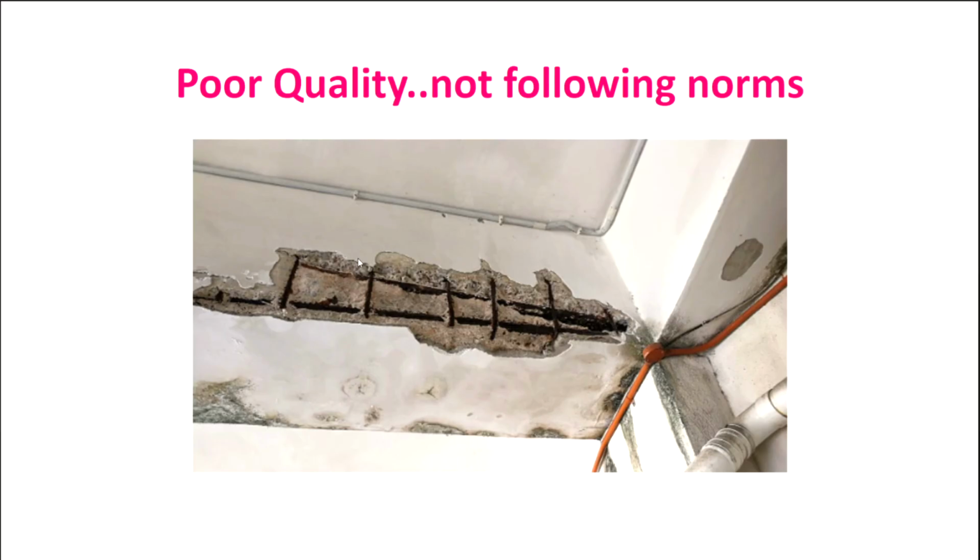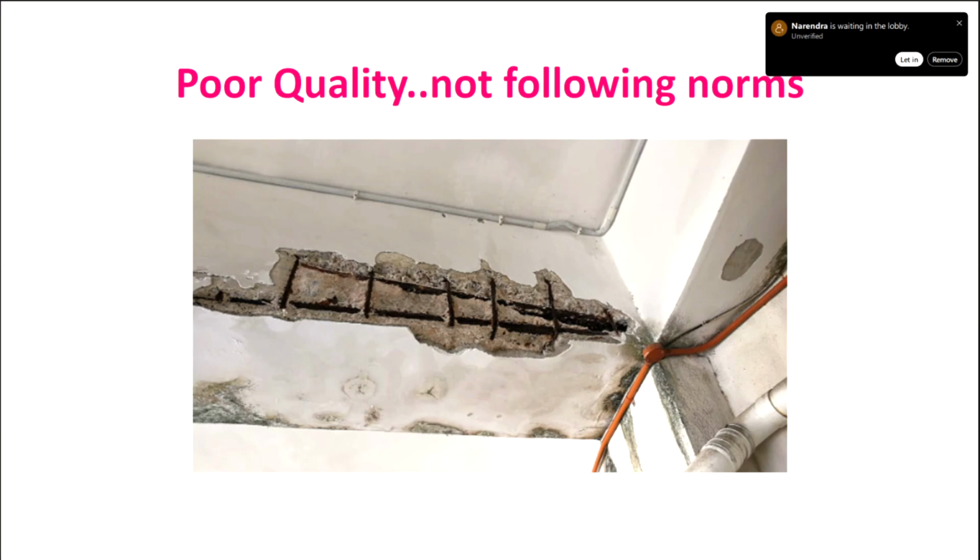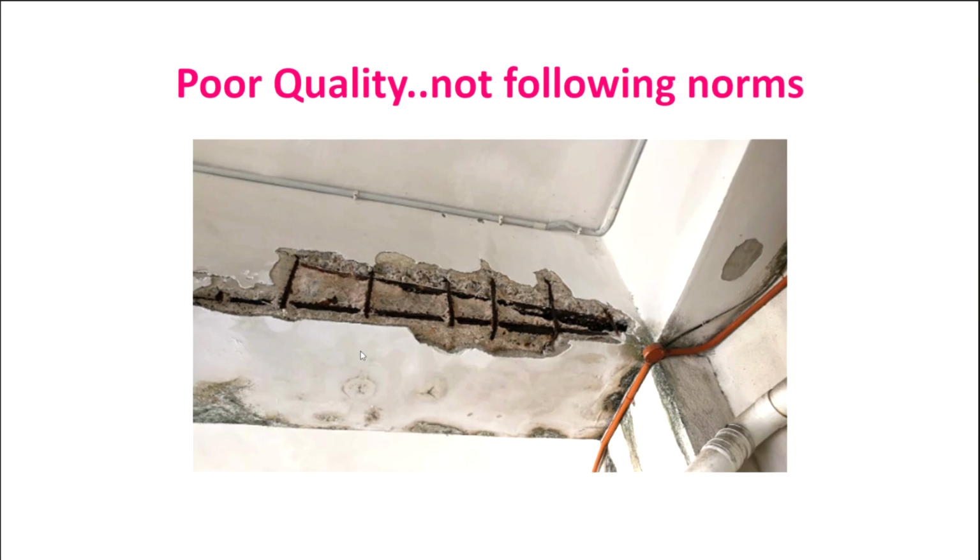So again, as you can see, it is exposed, and the reinforcement is already in corroded form. That means the cracks might have appeared earlier also. Suddenly it cannot go on, this corrosion aspect. So earlier it must have had some cracks, no proper attention was given to that, and now this condition has come. Now the falling has started. The falling is not an instant process, it will take some time. So as you can see in the works manual also, every building is supposed to be inspected.